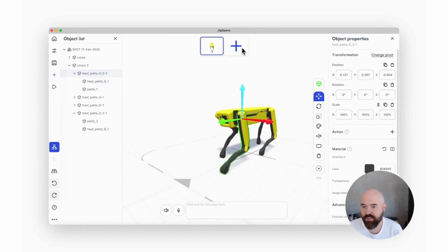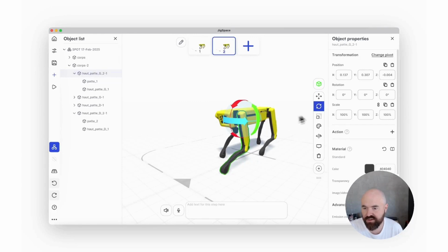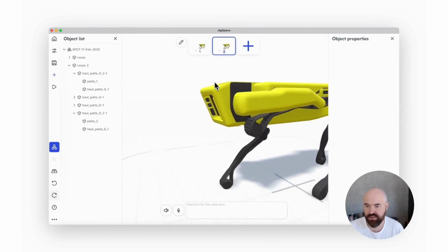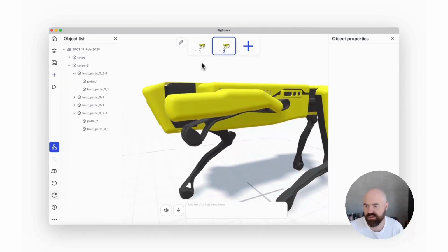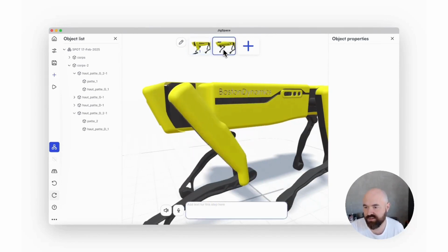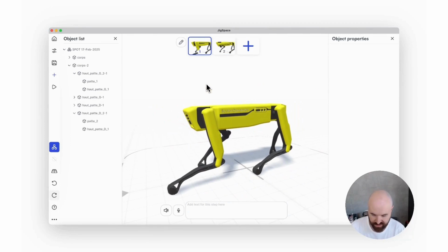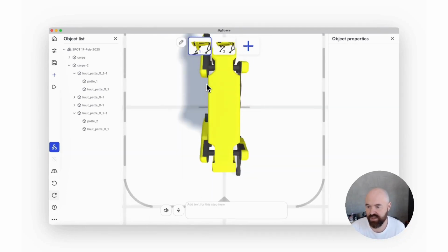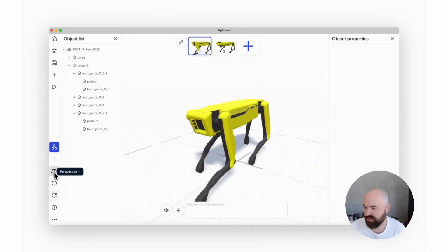And now if I want to do a couple steps of articulated movement, I can rotate this up here and then click on my lower limb here and fold that up there. And when going from step 1 to step 2, you'll see how they nicely move together as parent and children objects. And just as a reminder, those keypads are 1 for the standard perspective, 2 for top, 3 for side, and 4 for front. And you can also just press the camera perspective here.